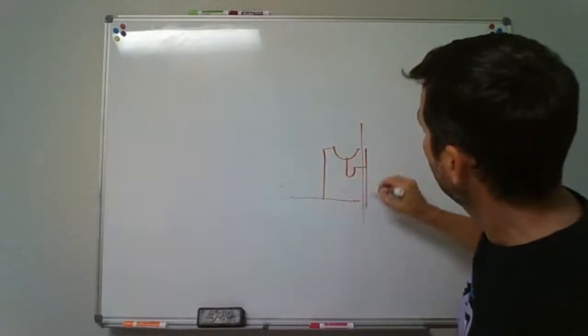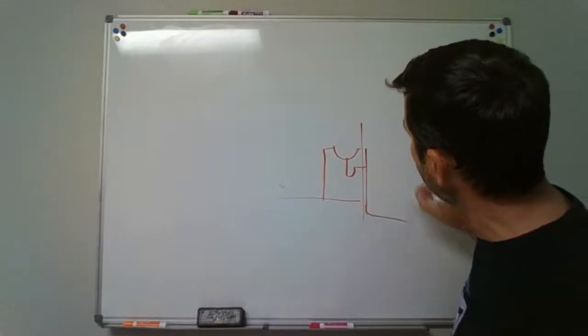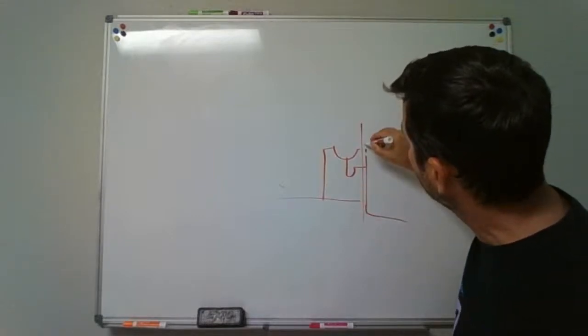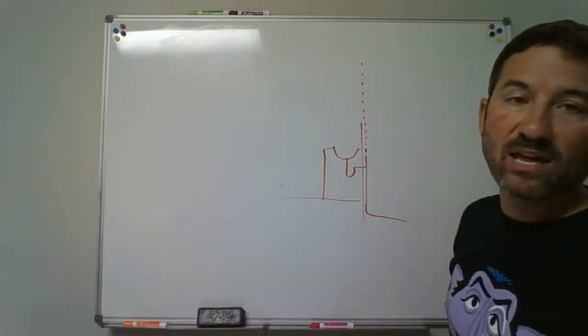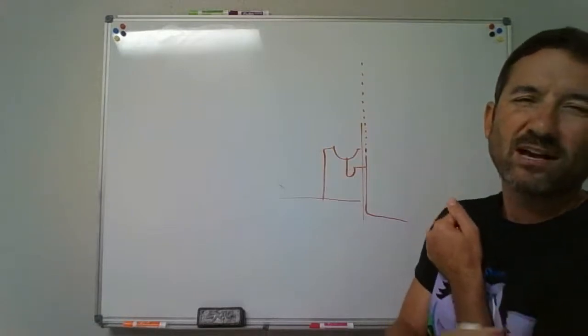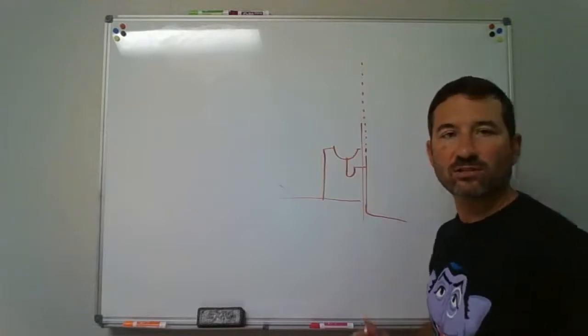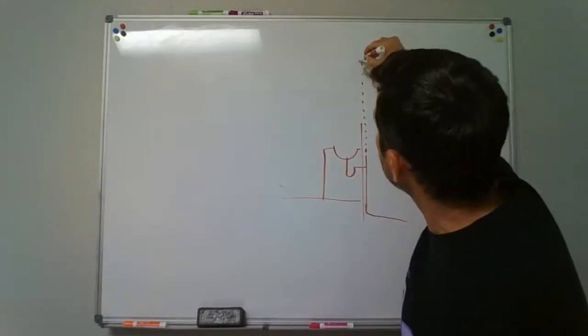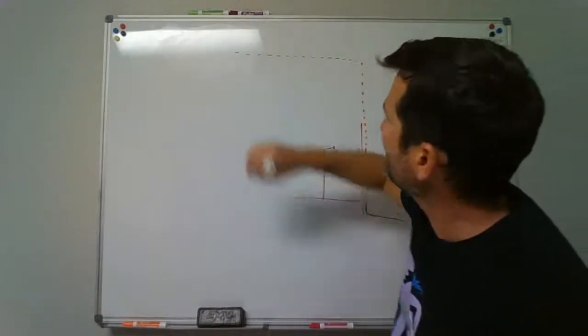There's our floor. Okay, there goes the drain, down and out. Here goes our vent. The vent goes up. But maybe we don't want to take that vent out right there, because if we went straight up through the roof, that might be on the front of the house. And we don't want to see that vent on the front side of the roof that faces the street. So we might just say, let's run that vent in the attic across to the back side of the roof.